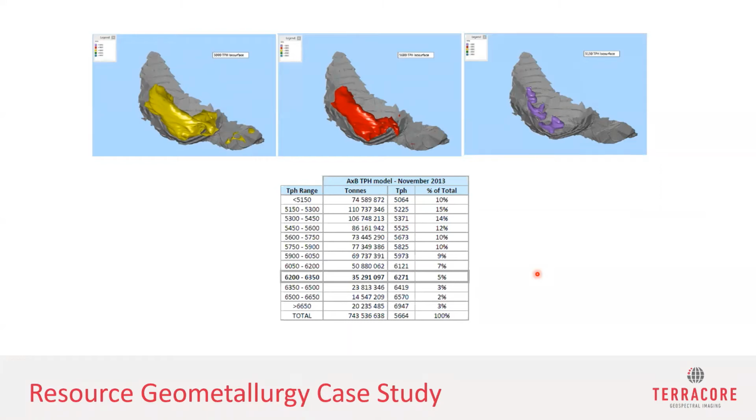And then using the bond index, we could look at what would happen in the bond index. So the original plant design called for 3 separate lines of crushers, primary, secondary, and tertiary crushers, followed by a giant SAG mill, followed by 2 ball mills. And then all of that going into a whole ore leach seemed to be the most effective way of recovering.